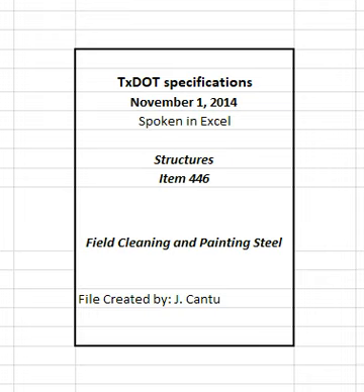Contain solvents and remove material as approved. Dispose of properly or reuse solvents as approved. This requirement applies to all coats. When abrasive blast cleaning is required, blast all flame-cut edges to produce a visible anchor pattern over the entire flame-cut surface. Completely remove, as directed, the protective coating on machine surfaces and pins.